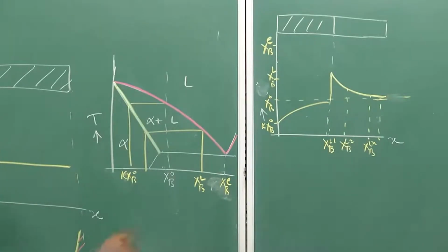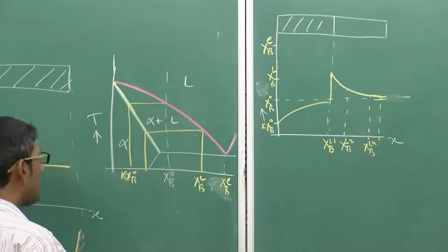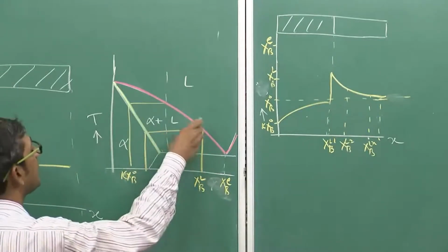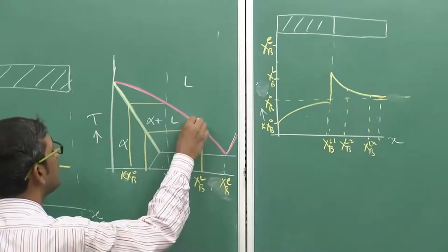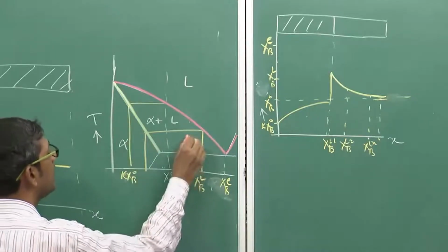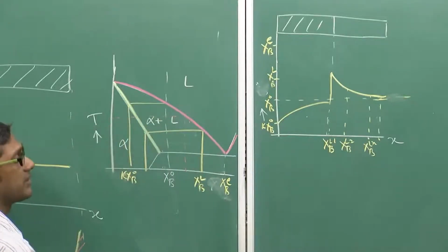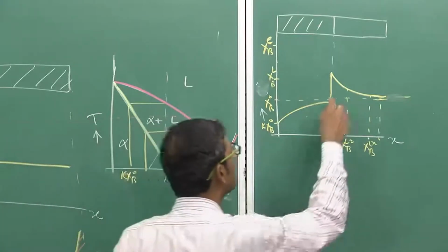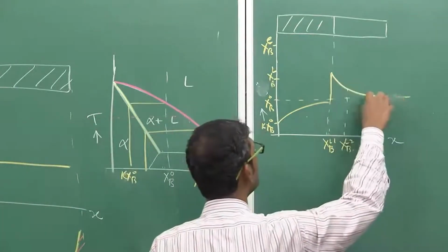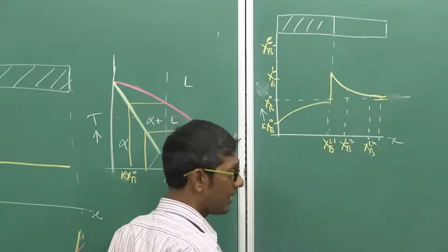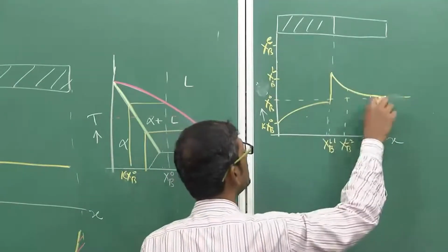As you clearly see, this is a temperature versus composition plot. That means, for any composition on the liquidus, I can determine the temperature. If I know the liquid composition, I know the liquidus temperature. The composition of the solute in the liquid is given by this profile, which looks like an exponential; I have given the equation also.